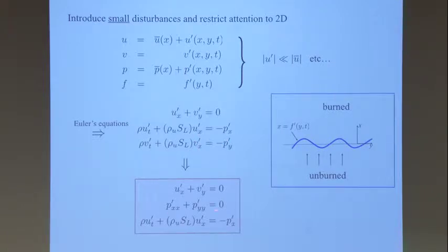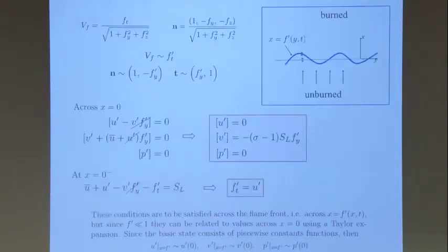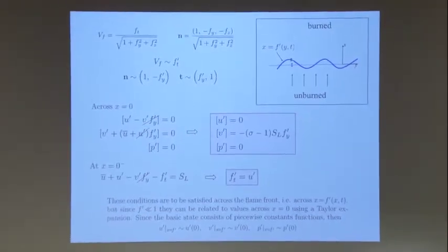So the Laplacian is 0. So an easy way to compute things is you solve Laplace's equation for the pressure, then you compute the u velocity from the momentum, and then the v velocity from here. Okay, so this is a detail, and one can easily do that.